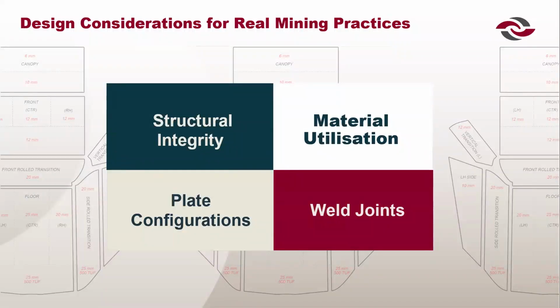This is why our design considerations go far beyond the CAD models. Structural integrity comes first. We use advanced FEA tools to identify the stress points, reinforce high load zones, and validate life predictions. Double-sided welds are used in critical areas, avoiding weak points that fail prematurely.